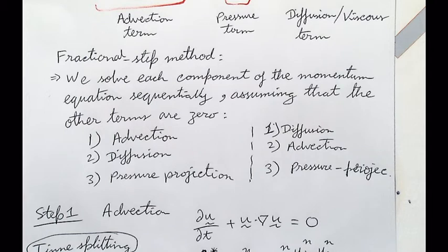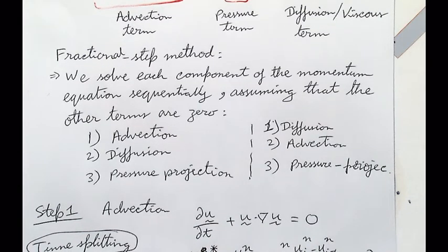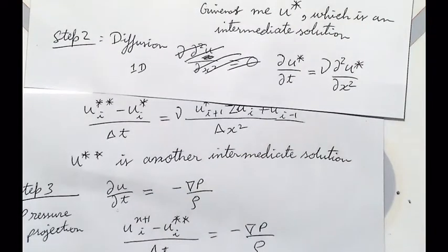It's completely valid. But in this fractional step method, we are not using that at any point. We have not solved any Poisson equation yet. All we have done is solve the advection, diffusion, and now we will see what is the Poisson equation that we need to solve. Okay, so, but what you're thinking, I don't know how well it applies. Pressure projection is the fastest.